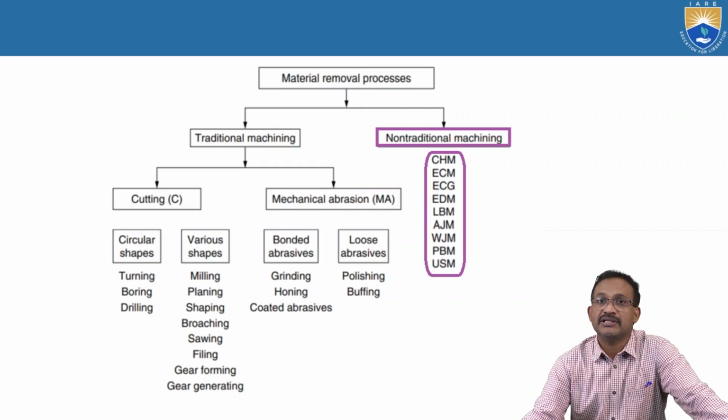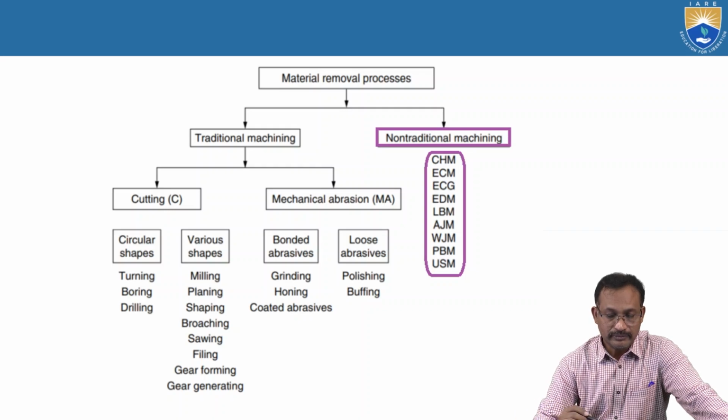That is the main difference between turning and boring. So in turning, the workpiece will revolve about its own axis, and in drilling or boring, the workpiece material will be fixed and the tool will rotate and enforce into the workpiece for the material removal.